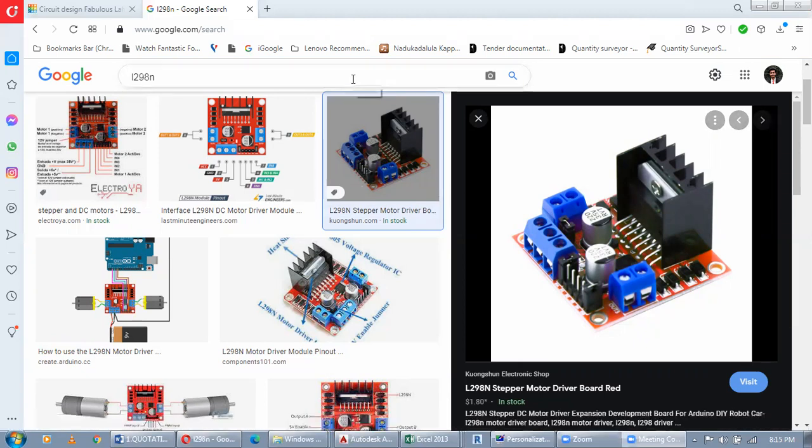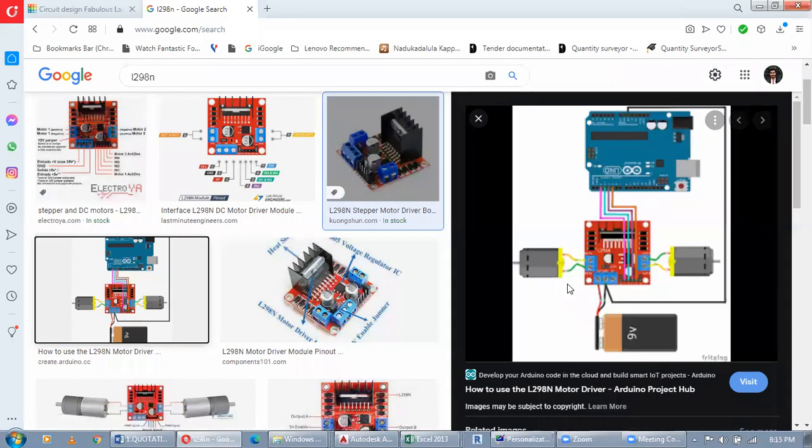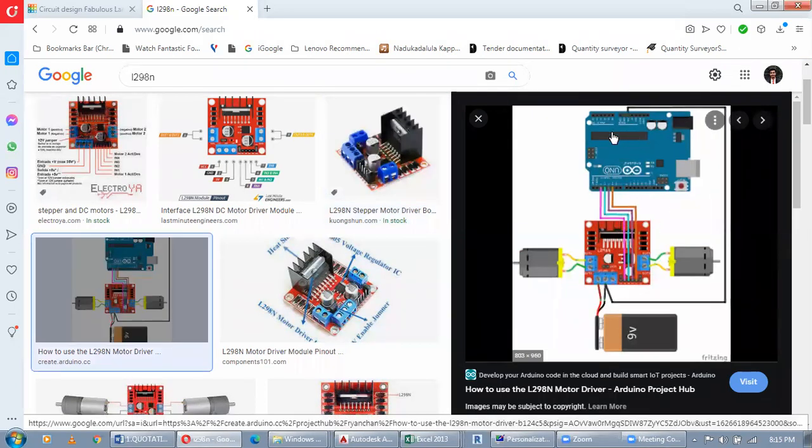So this is simple, right? Because here in this diagram you can see the Arduino. I showed the Arduino, what it will look like. This Arduino can control only 3 to 5 volts. That means it controls the components by providing signals, right? Electrical signals, and those electrical signals are small in amount. That means we can obtain only a small current from Arduino, so we cannot obtain the large current that can drive the motors, right?